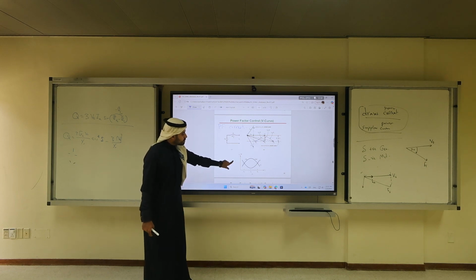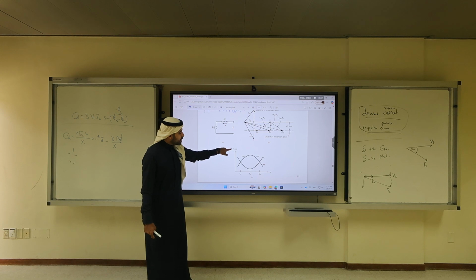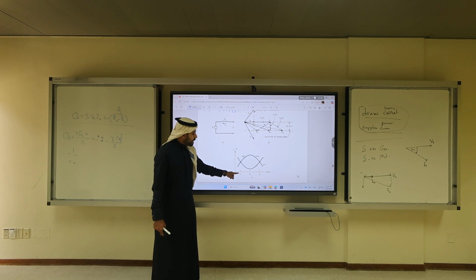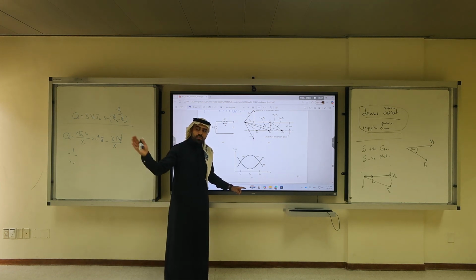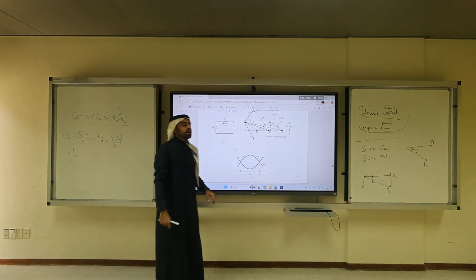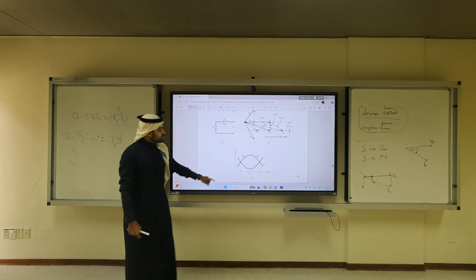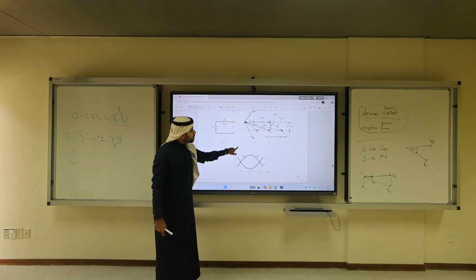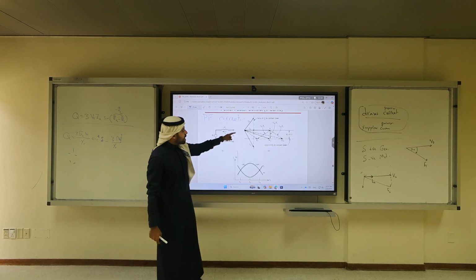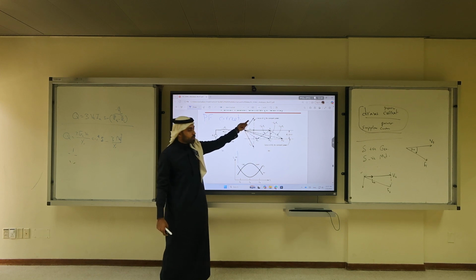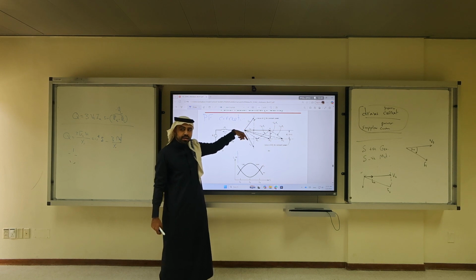If I plot the armature current, IA, with respect to IF, remember, IF corresponds one-to-one to EF, because we're operating at the linear region, not the nonlinear. So if I start from a small IF, I might have a bigger IA. This is the armature current. In magnitude, it's big, then smaller, and then it goes back to big. The only thing that changes is the angle.